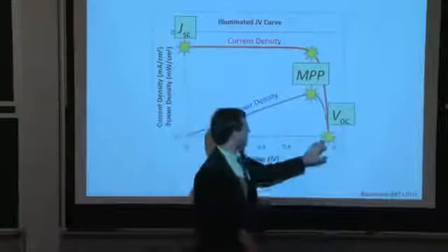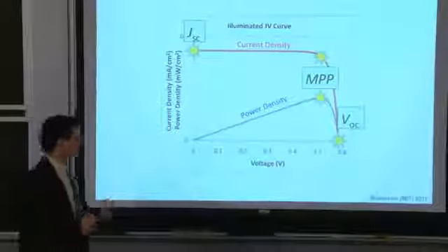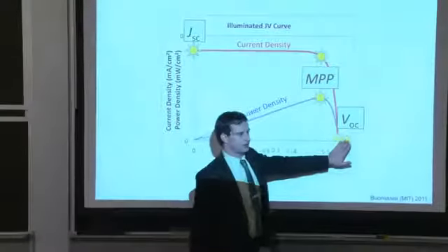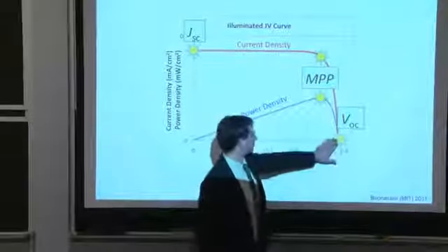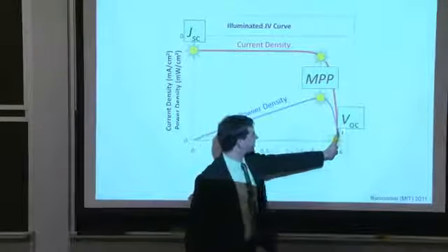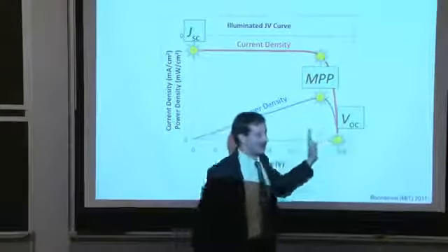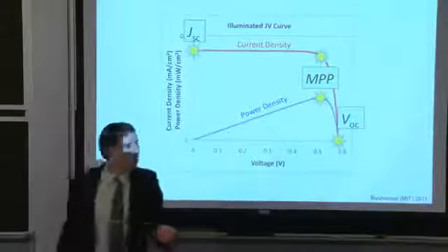And I can show you a very nice little paper that describes why that is. It essentially has to do in part with losses inside of the solar cell, thermodynamic limits of conversion inside of the solar cell device. Then what we've done is another additional discounting from the VOC to the maximum power point, which we've assumed is around 0.1, maybe 0.2 volts.